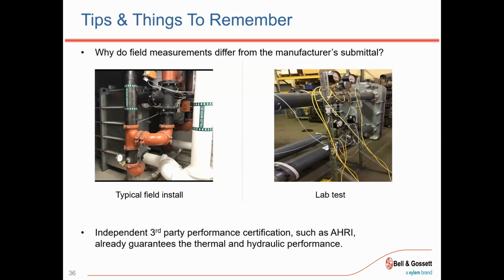All these units are tested in lab conditions, and often you go to these sites and we have all these different measuring tools on the heat exchangers for a specific application, but there are fittings right before that where we're reading pressures. If you have an application that is highly sensitive, we have recommendations for straight pipe depending on the item. You just want to make sure that you have uniform flow, without any turbulence or distortions that would impair the readings.